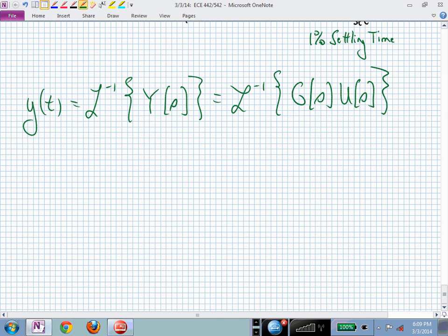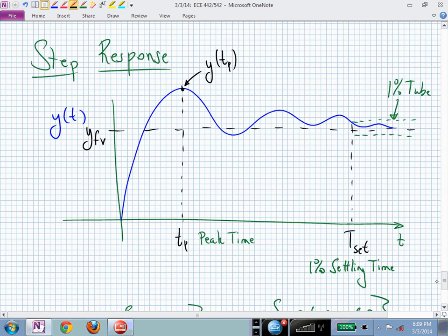And if I wanted the time to peak, if I ask you to find that, and now just sort of transport back into a calculus class, hint, hint, how do you calculate the time to peak? How are you going to find this t sub p if you know y of t? If you know a formula for y of t, how can you find t sub p? You differentiate y of t and set it equal to 0, don't you? That's where it hits its maximum.